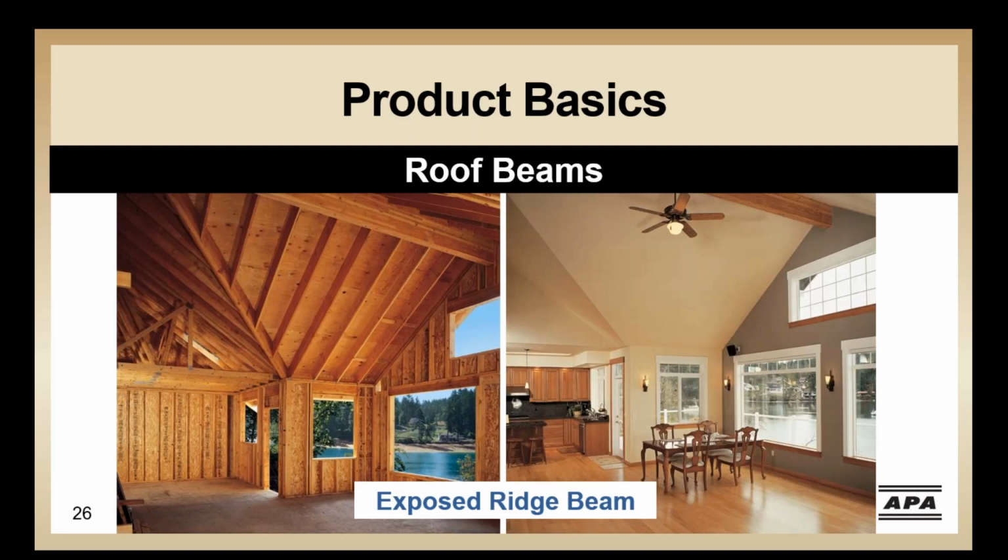While all these products can be used as ridge or ceiling beams, how the beam is exposed will influence your beam choice. All these beam products could be suitable if the beam is not exposed, buried in an attic, or wrapped to create a faux wood finish, for example. On the other hand, if an exposed beam is desired, an architectural or better grade of glulam can be used, or even some structural composite lumber has good wood characteristics that many people like, and they will leave those exposed as well. These beams can be stained and coated to bring out the beauty of the wood. Notice the ceiling fan hanging from the beam. We'll talk about that a little more in a bit.